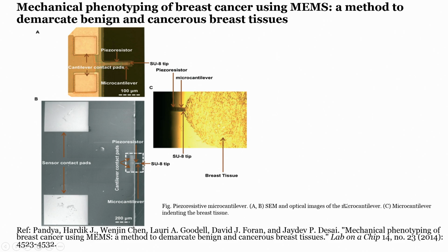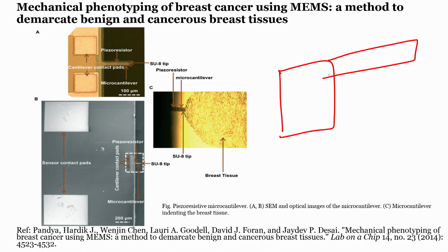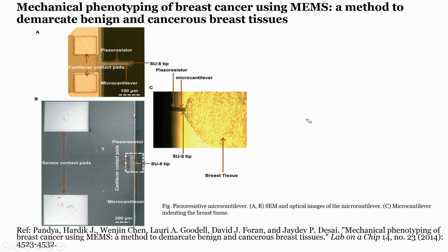So, let us go to the next slide, and next slide is a very important slide, because here what we are understanding is how to design a piezoresistive microcantilever. You see, if I have a diving board, right, in a swimming pool, this becomes a cantilever. Now, we are talking about a cantilever which has a thickness of about just 2 microns and with a width of about few hundred microns, and there is a piezoresistor embedded or integrated onto it.